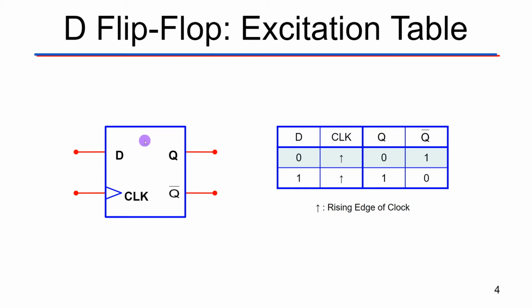And then what we're actually doing here is we're going to take that signal in, that D, and on the rising edge, right, when we go from 0 to 1 on our clock signal, that rising edge, we're going to take the value on D that's currently there, and we're going to store it to the flip-flop. And anything that we have stored here, remember, we can only store a single bit. So this is either going to be a 0 or a 1 on that rising edge. It writes it.